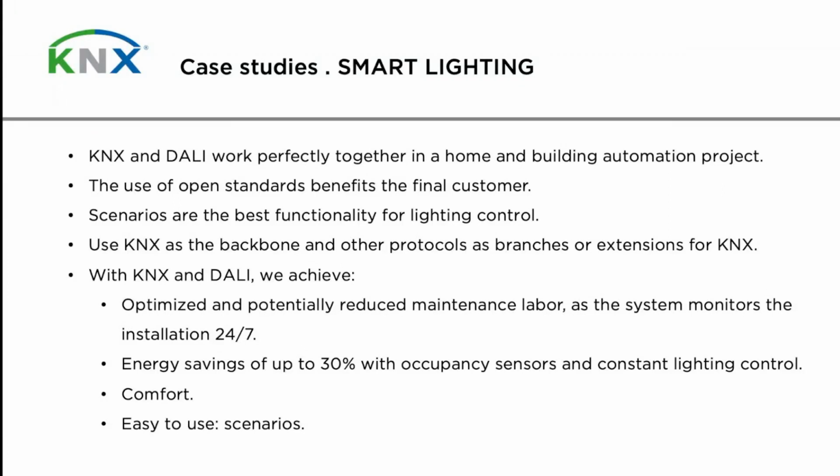Scenarios are the best functionality for lighting control. As I said before, do not use DALI and KNX to switch a single light or group of lights on and off. You can do that with conventional electrical installations. Don't do that with KNX or DALI, please. Try to get the most out of the system. Why? Because otherwise the customer will say KNX is very expensive, DALI is very expensive. Of course it is, just to switch lights on and off. Absolutely. Use KNX as the backbone and other protocols as branches or extensions of KNX, okay, as I showed you before.